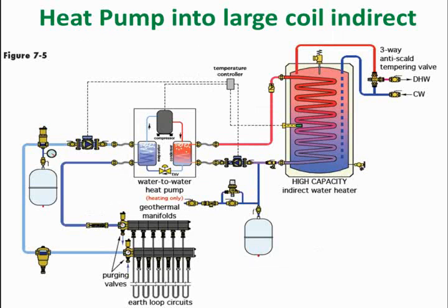We had a couple others in here that I want to show you. This is another way that you could cover loading into a tank, but using the coils instead of the tank capacity. We happen to have a solar tank that does have large diameter coils. Our coils are 1.5 inch diameter. We've got, I think, 36 feet of coil on the bottom, 30 feet at the top. They could be combined together here, so you can have 66 feet of coil going from the bottom all the way to the very top of the tank.